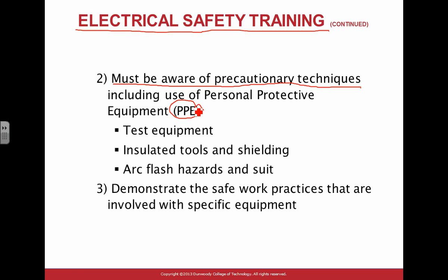When you did the hazard analysis for 3M and you said, yes, I do work on energized objects or equipment, then question number 2 is, okay, great. First, are you qualified to work on it? Yep, I'm qualified, I know how it works. Good. Next, do you know how to pick the proper PPE to work on it, based on the shock hazard and the arc flash hazard? That's why you guys are here, because we walked through that one.